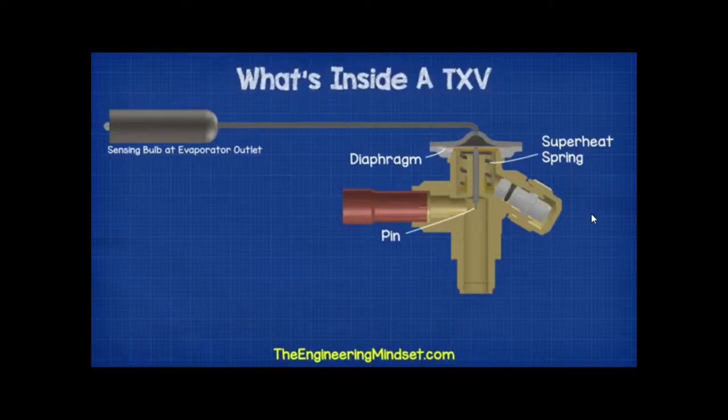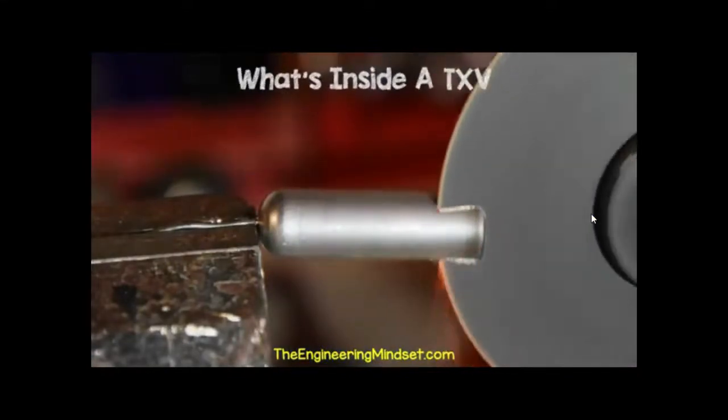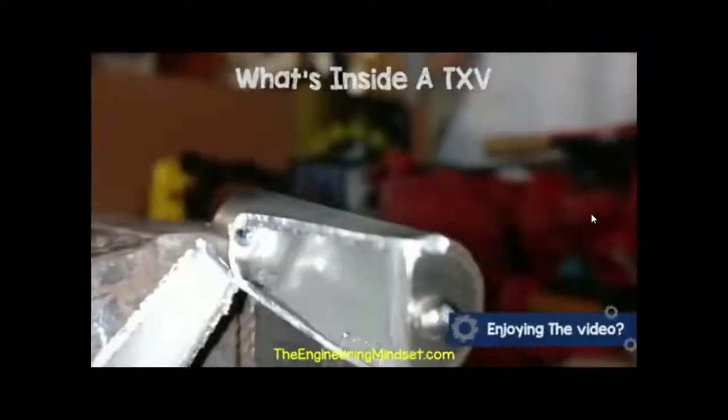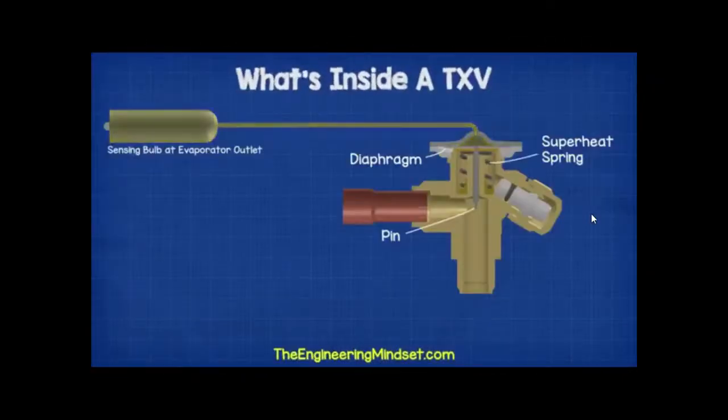Above the diaphragm, we have this empty chamber which is connected to the capillary tube and then the sensing bulb. The chamber, the capillary tube and the bulb are all hollow. I'll just cut through the sensing bulb using an angle grinder to show you the inside. As you can see, it's just an empty cylinder which is usually filled with some refrigerant. The refrigerant in the bulb and capillary are completely separated from the main refrigerant which flows in the system. This isolated refrigerant only moves between the bulb, the capillary tube and the top of the diaphragm.